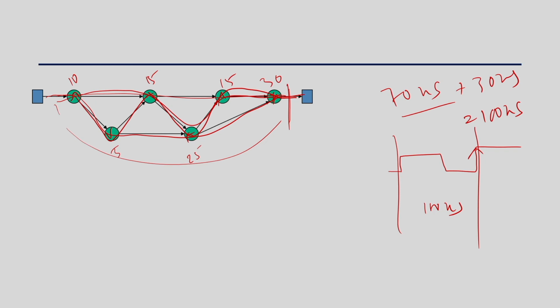So, if I take this particular circuit, and since I found that the longest combinational path is 100 nanoseconds, my clock period should be at least 100 nanoseconds, which is basically 1 by 100 nanoseconds, so 10 megahertz. This is the clock speed. So this circuit won't run at more than a 10 megahertz clock, right.